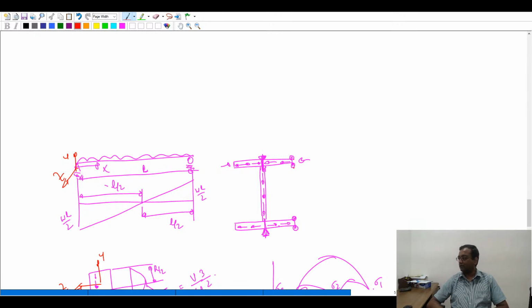Triangle and circular sections are difficult to construct in practice using reinforced concrete. So they are not preferred. Circular section again is not so beneficial for bending resistance, because more material is towards the center and less of it is towards the outer surface. An annular cylinder will be a better option as far as bending resistance is concerned. So efficiency of material utilization and ease of construction determine what cross section a beam is designed to have.